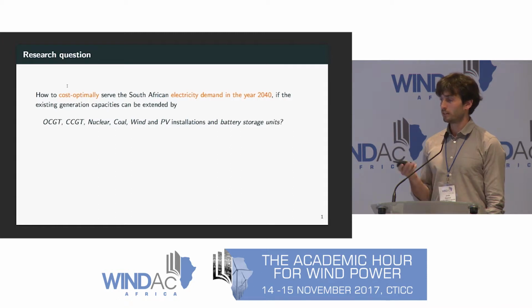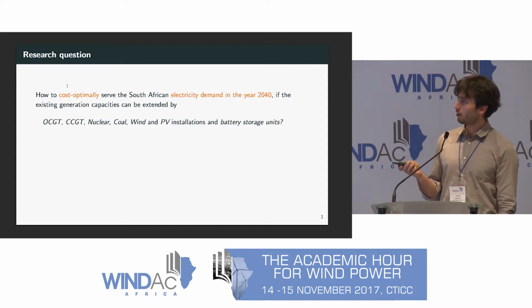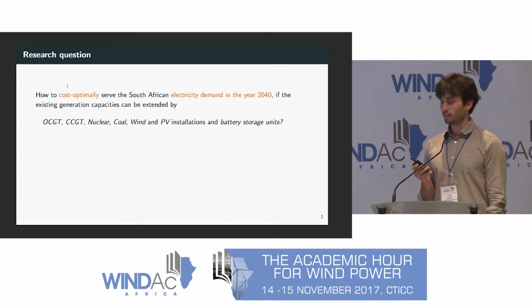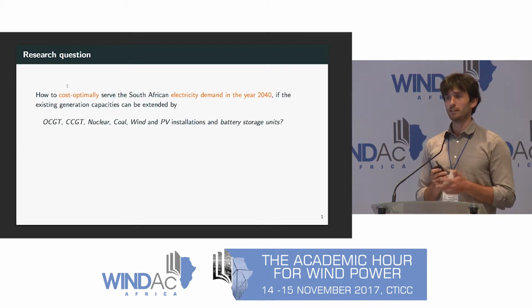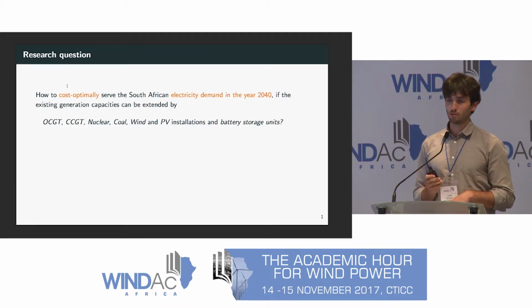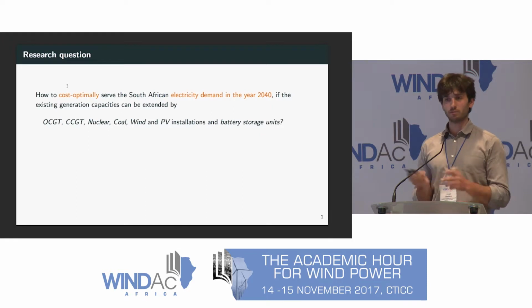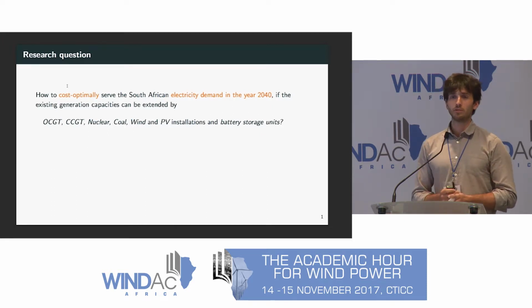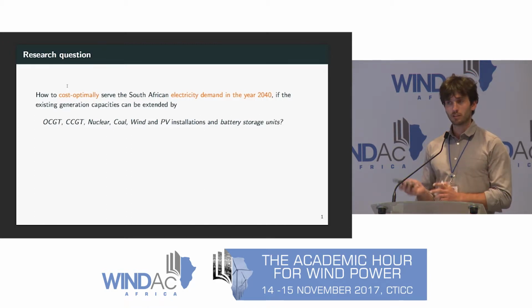And since there are now varying energy sources in there, it's not really the same way it worked before, that you just take the peak demand and then add some extra margin on there and have your generators which can provide this peak demand, and then perhaps do some kind of extra grid studies.